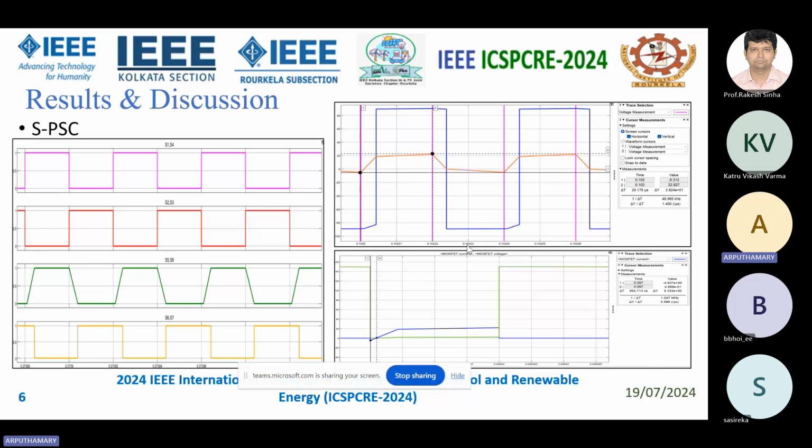Accordingly, I am calculating the circulating current present in the high frequency transformer. Here, by using the single phase shift, I am getting a magnitude of circulating current of 22.92 amps. Similarly, the ZVS range is only 954 nanoseconds, which is very less.